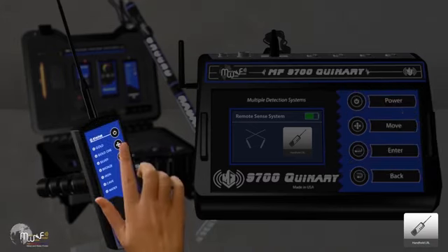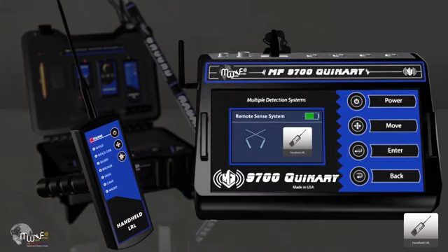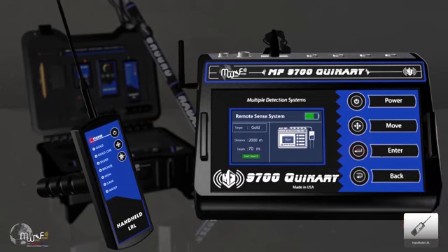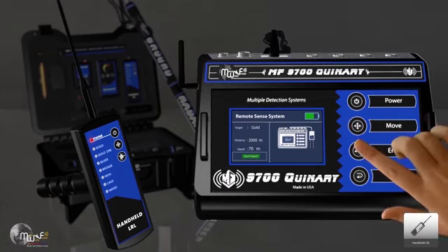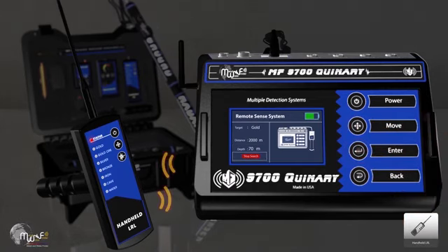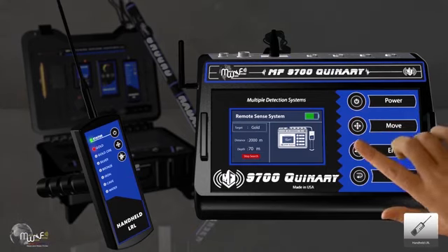First, turn on the LRL unit, then go to the main unit and choose the search criteria of this system. Then press Start Search to connect the main unit and the LRL unit. You will notice the color of the status LED change from red to green.